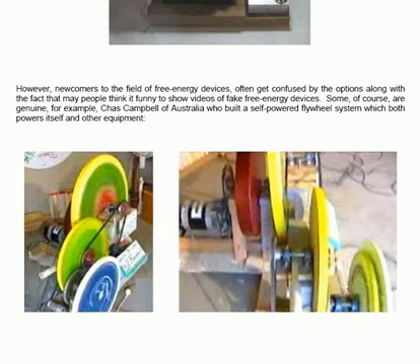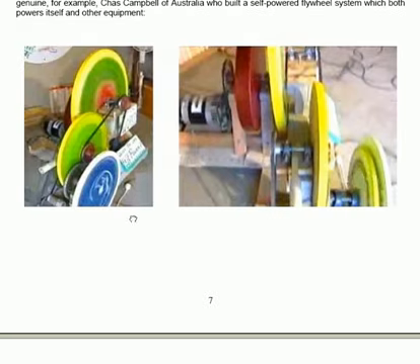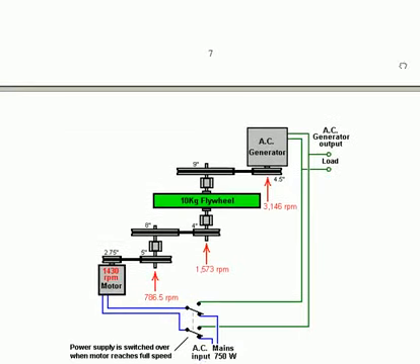The circuit that is involved in this is very straightforward. You have the motor, which is a 1 horsepower motor. It spins a pulley wheel, which is connected by a drive band to another pulley wheel, and that is continued up here, and a 10 kilogram heavy flywheel is spun by the system. That turns a 9-inch diameter pulley, driving a 4.5-inch diameter pulley, powering an alternating current generator.